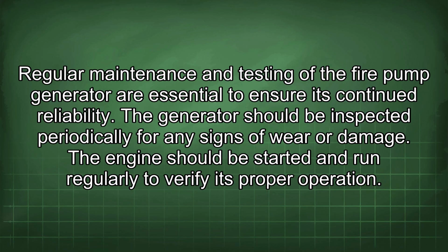Regular maintenance and testing of the fire pump generator are essential to ensure its continued reliability. The generator should be inspected periodically for any signs of wear or damage. The engine should be started and run regularly to verify its proper operation.